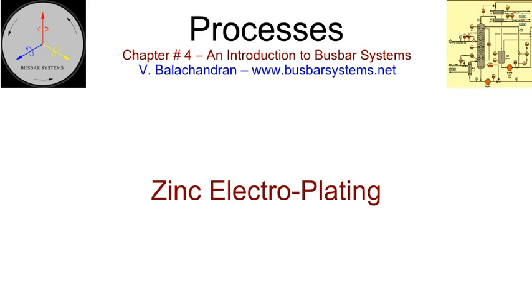The plating solution was mostly cyanide, which is highly hazardous to health. It is now being gradually replaced by non-cyanide or acid chloride salt solution. The zinc electrode gets dissolved in the solution and gets deposited on the component. The thickness of the coating is low and does not increase beyond 25 microns. The surface is subsequently passivated to give extended life. Some of the components such as nuts, spring washers, and Belleville washers need heat treatment to relieve stress.